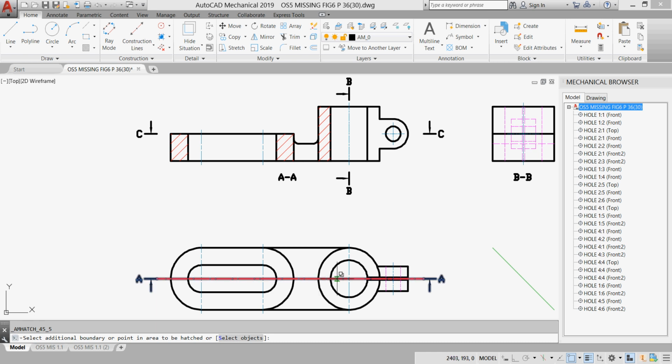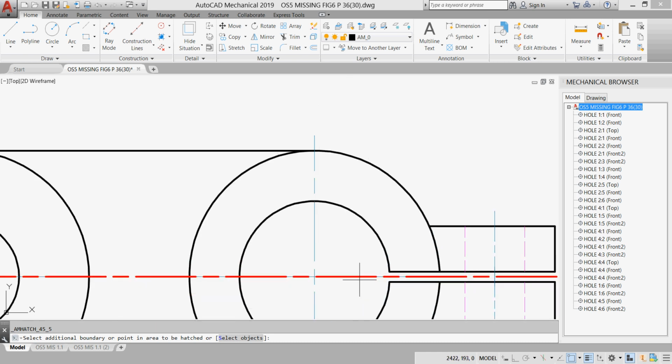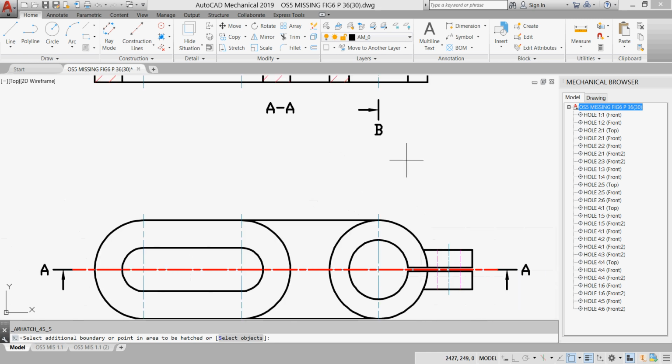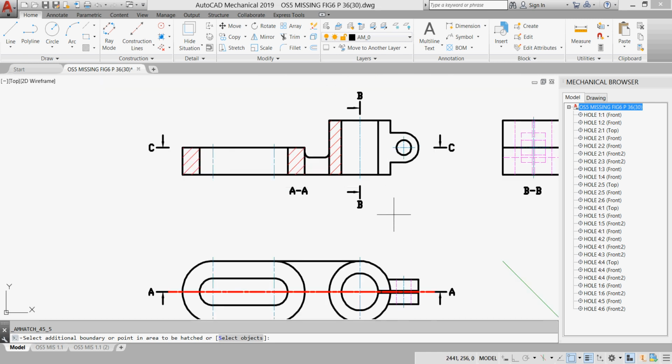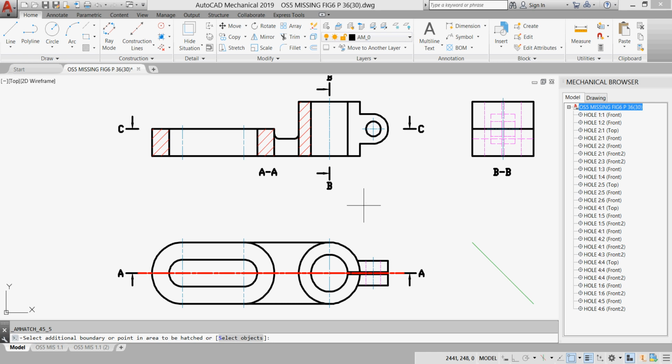And here we have the thickness of my cylinder and hole. When we look here, it's open. So it didn't cut. It goes away there in the front of the cutting plane. So we didn't put hatch lines here. That's why. This is the sectional front view of my object. Okay. Let us see what we'll have in the side.